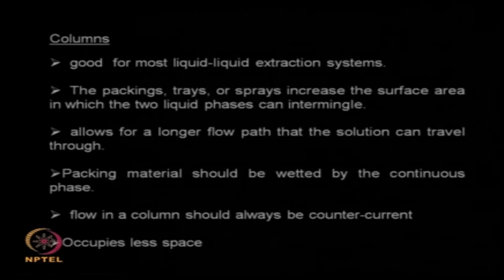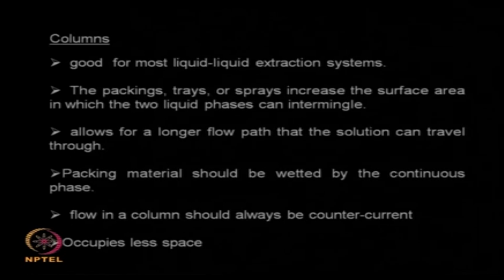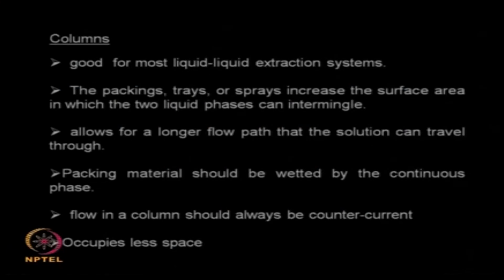Actually, columns are tall structures where you are bringing both your solvent and the heavies either in co-current or counter current fashion. They get mixed thoroughly because you will have trays or you will have packing inside the column. So, during those mixing stages inside the column, the partition of the solute takes place.